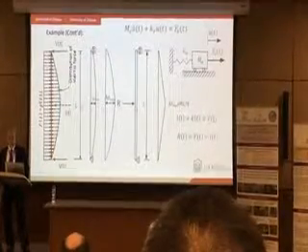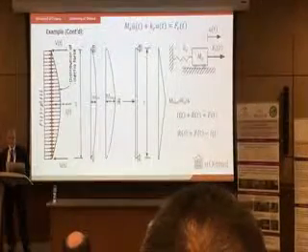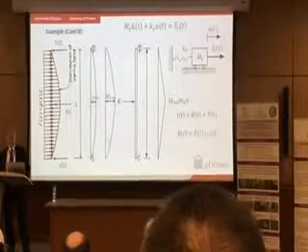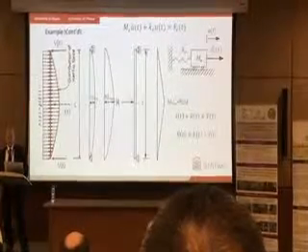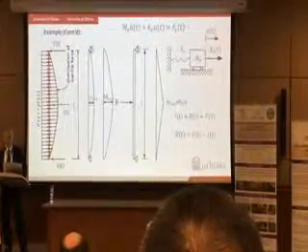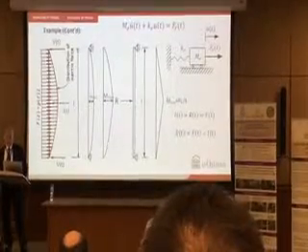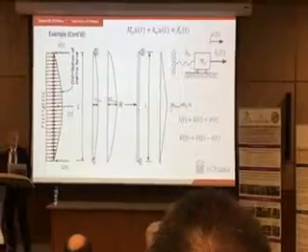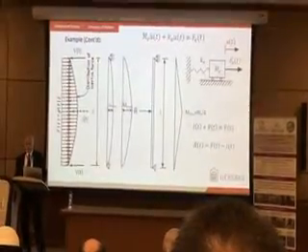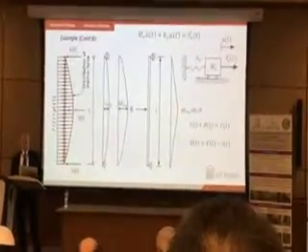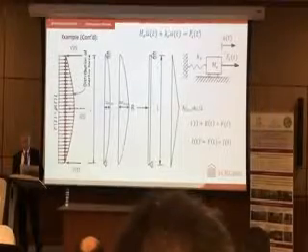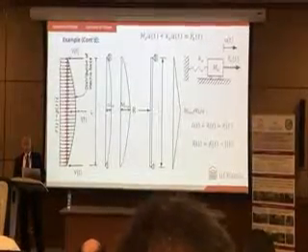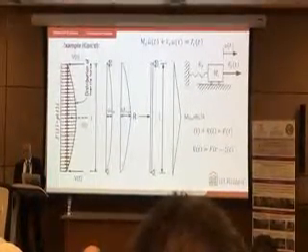So the resultant deflection is here, and this is the moment diagram. But I utilize idealized mass and force, so I treat it as if it's a concentrated load and lump mass, and I get the maximum moment. But this shows you that resistance is equal to applied force less the inertia force.